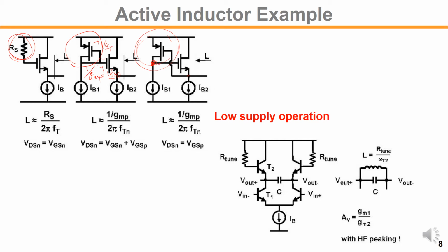This node is connected through the follower stage. In AC, since this output will follow the gate voltage, it seems like a connection. So this has a constant voltage drop VGS there. In the small signal sense, the output follows the gate, so this looks like a connection.